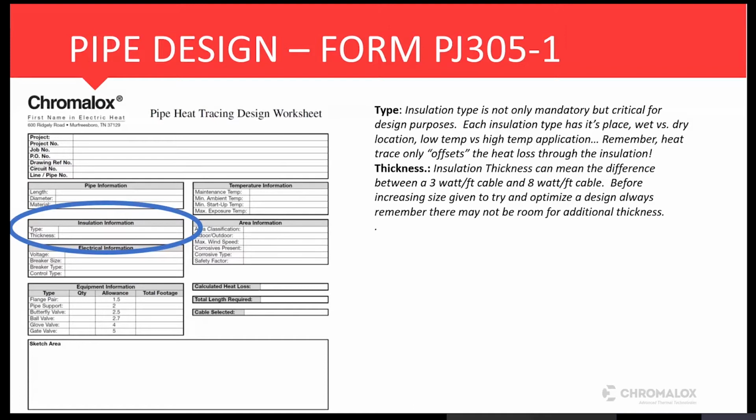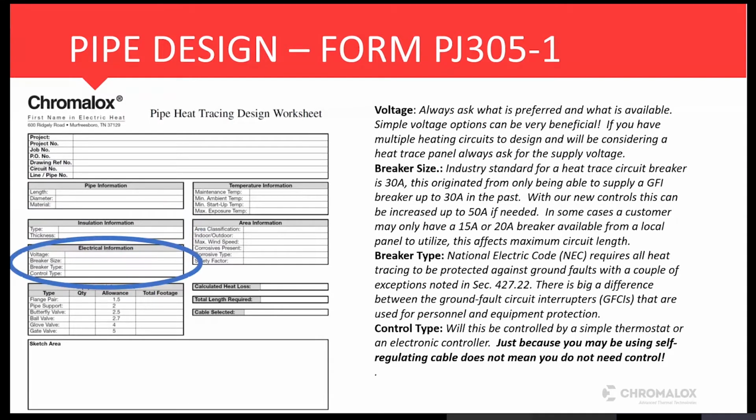Voltage, as you know, we sell electric heaters. Voltage is one of the first questions we ask. But I always ask two questions. I ask, what is your preferred voltage, and what is available? If their preferred voltage is, well, I've got a 120 volt, or I've got 208, well, do you have 277 available?